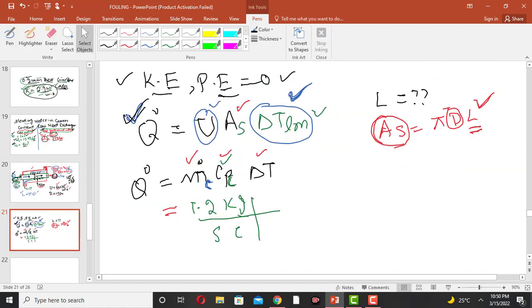So at 50 degrees centigrade, the specific heat of the cold water will be 4.18. You can obtain it from literature or from graphs or from other tables given in various books. So 4.18 kilojoule per kilogram Kelvin. This is the specific heat of cold water.